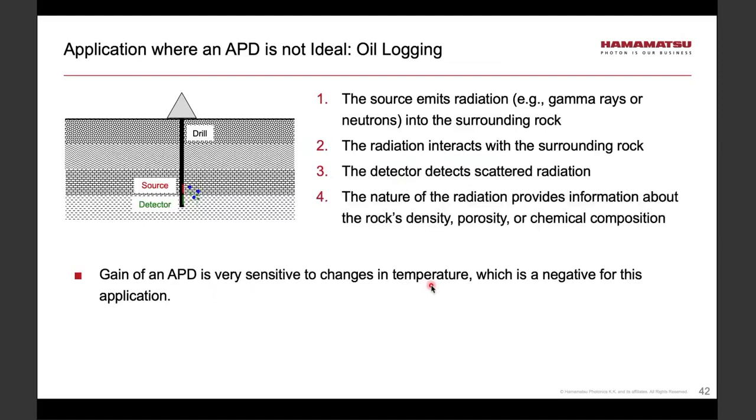We've mentioned oil logging before. APD would not be a good choice because its gain is highly sensitive to temperature, and the temperature here can be quite high. After all, it's oil logging. Drills are drilling into a rock.